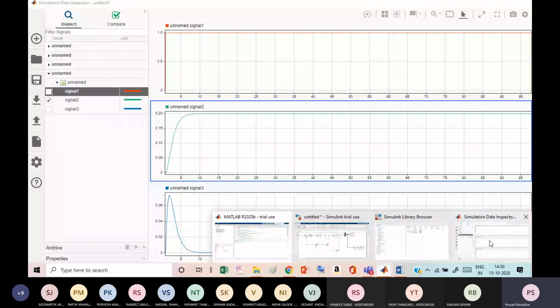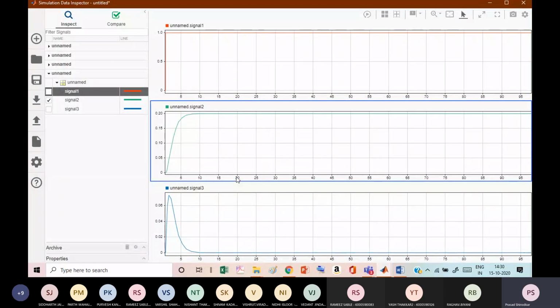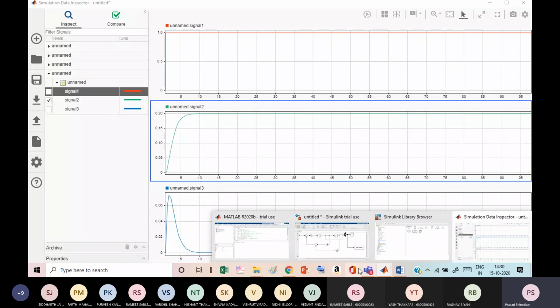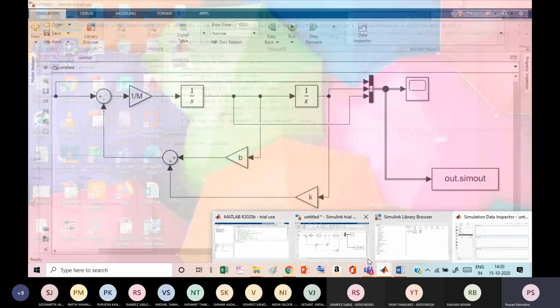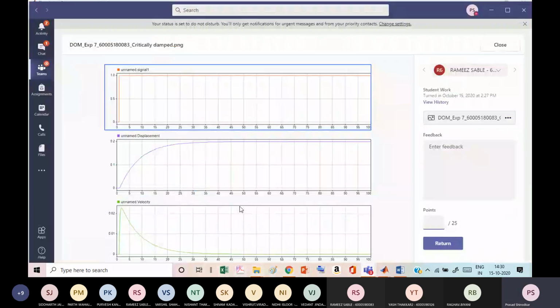You are getting a result which is similar to the graph which I have shown, right? So why is it similar? Can you answer? It's an overdamped system. Correct. If you check the zeta value, it is greater than 1. So that is fine. No need to change the response. What you have plotted is in fact not a critically damped system. It is an overdamped one. Yes, sir.